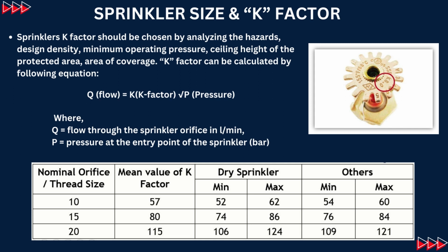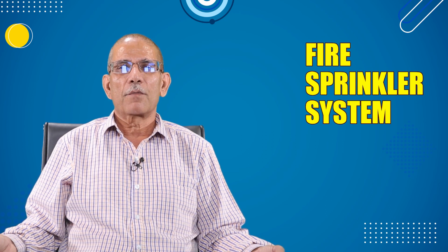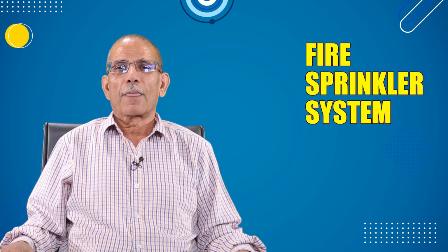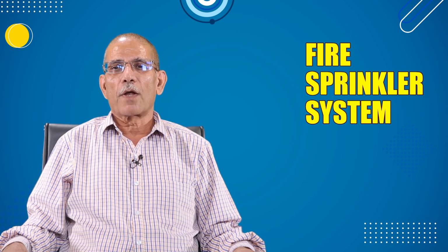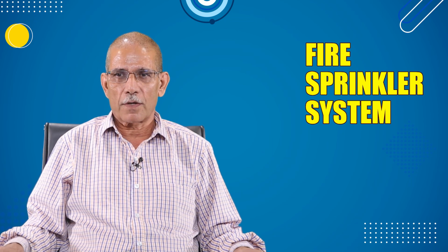If the nominal orifice size is 20, which is normally the maximum size, then the mean value of K factor shall be 115, whereas for dry sprinklers the minimum is 106 and the maximum shall be 124. For others, the minimum will be 109 and the maximum 121.